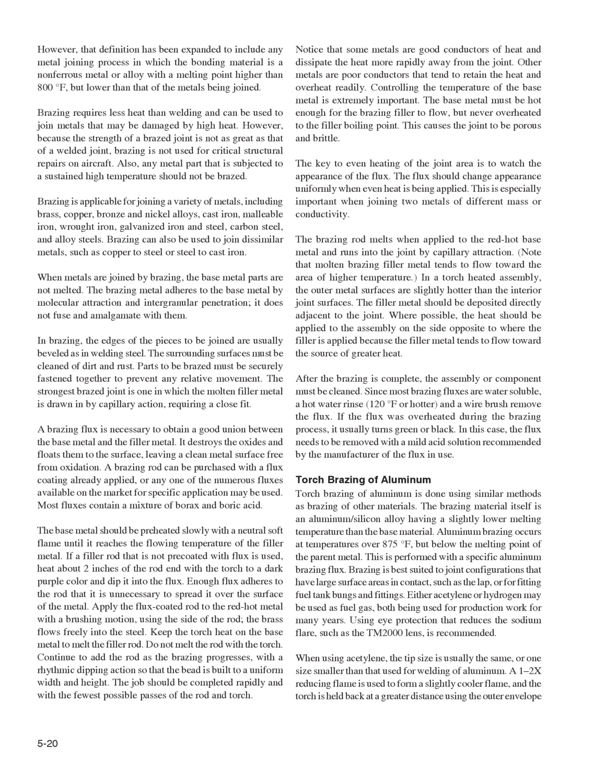In brazing, the edges of the pieces to be joined are usually beveled as in welding steel. The surrounding surfaces must be cleaned of dirt and rust. Parts to be brazed must be securely fastened together to prevent any relative movement. The strongest brazed joint is one in which the molten filler metal is drawn in by capillary action, requiring a close fit. A brazing flux is necessary to obtain a good union between the base metal and the filler metal.